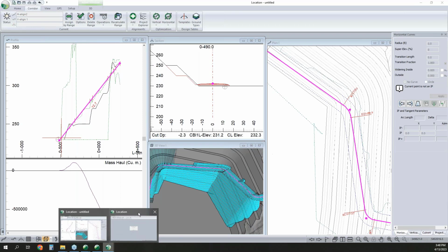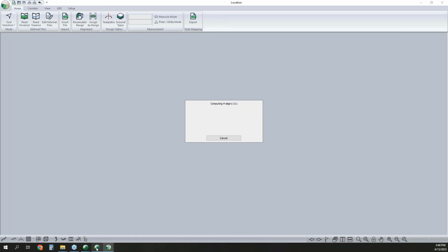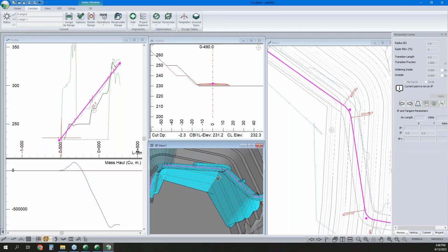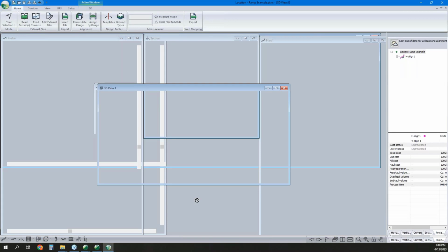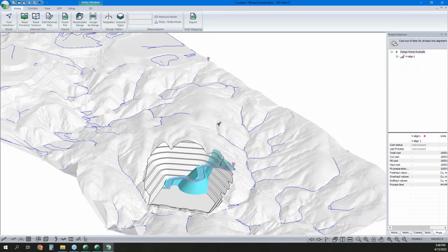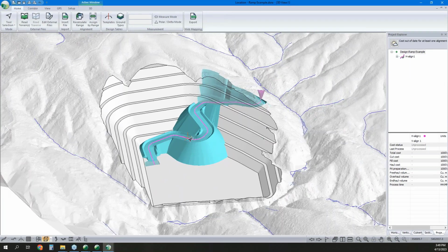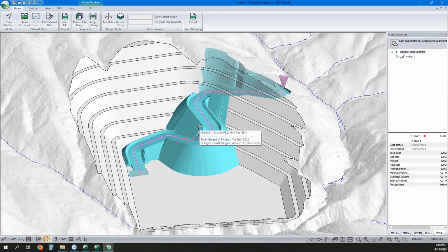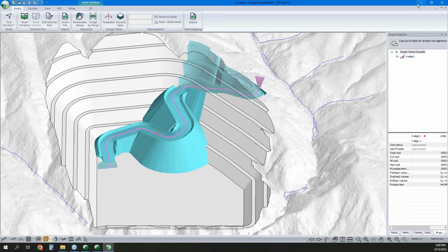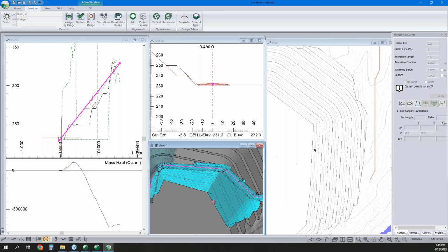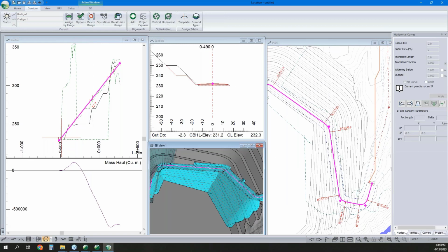And I mentioned I was, I'll let that run. That functionality of being able to make our cut and fill slopes a graded feature really opens you up to have more flexibility to do things like this, where we've got our fill slopes stacked on other fill slopes. Now with this, if we want to produce our documentation, we absolutely can.